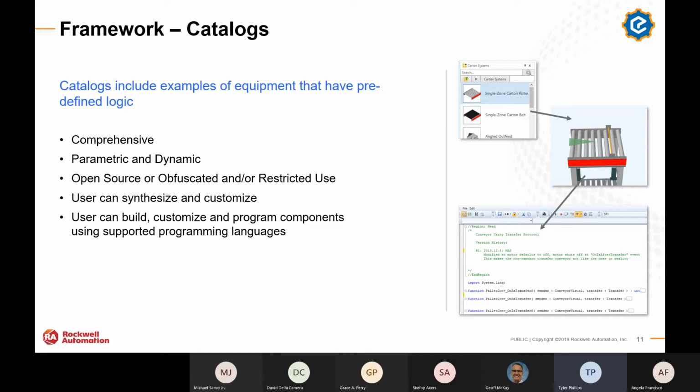It has a visual representation that looks like a roller conveyor, but it also has some smart equipment. It has motors. It has a photo eye. It has direction of travel. The rollers move, they have coefficients of friction, there's acceleration and deceleration and speed. And in addition to that, it has a logical representation in the script that's attached to it.